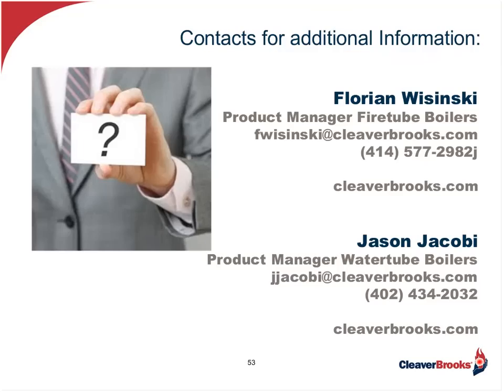All right, thanks, Earl. How do you recommend sampling the water prior to it being put into the boiler in order to increase efficiency? Well, we recommend sampling using a sample cooler. That can either be on a deaerator or feed tank, or it can be on the boiler itself. But normally it's on the feed system.